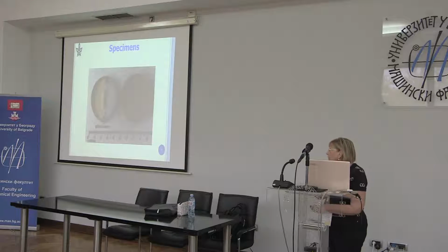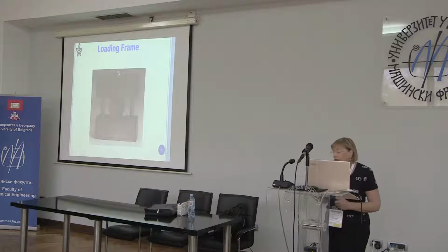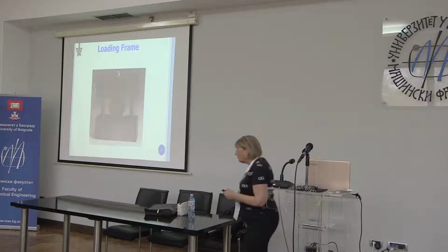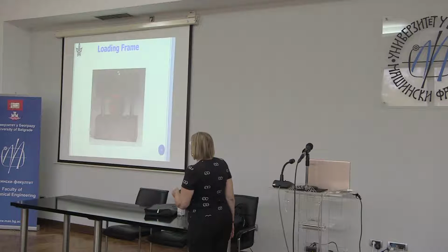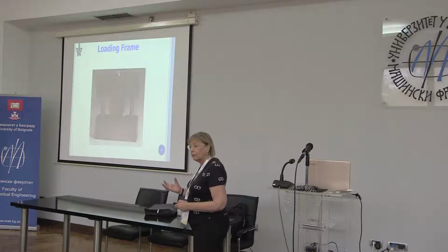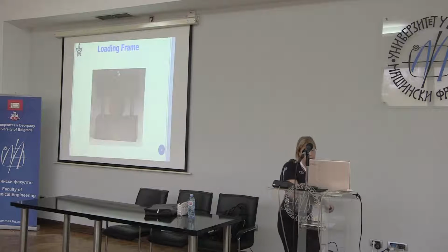So the ones on the left are glass epoxy, and the ones on the right, which you cannot see, are 2 ceramic clays. And so here, okay, you can see the specimen a little bit. This is a very deep orange. And this is our loading frame, and you rotate the specimen. The load comes along the vertical axis, and we rotate the specimen, and we get a whole series of different mixed modes by rotating the specimen with respect to the loading direction.